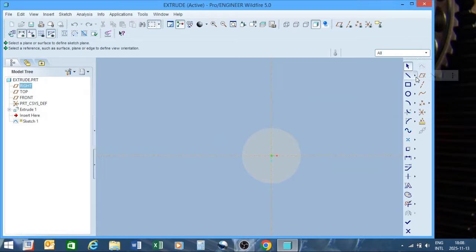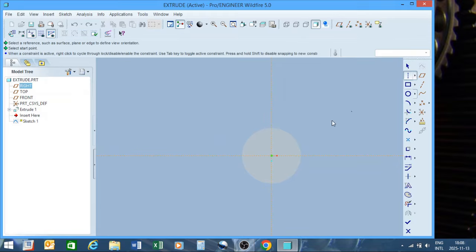It will turn it automatically as you saw there. Now, as I've said in my other sketch features or in other videos, center lines are very important in my opinion. It makes it a lot easier to draw squares, anything symmetrical, and 90% of the time symmetrical is king. Unless you don't want it symmetrical, obviously there are applications for it, but I'm speaking in general terms. So okay, we click the rectangle function, we click in the left corner, drag to the right till we see it's all symmetrical, we click again.